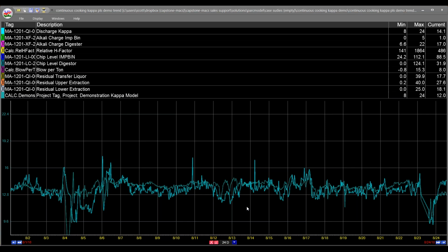In that case, you need a fairly long period of time, because let's say you're modeling using 10 process inputs, then you probably want 1,000 data points in your model. Of course, if you're only sampling a few times a day, that's several hundred days. So if you need 1,000 data points and you're only sampling twice a day, you need 500 days to get those 1,000 sample points.